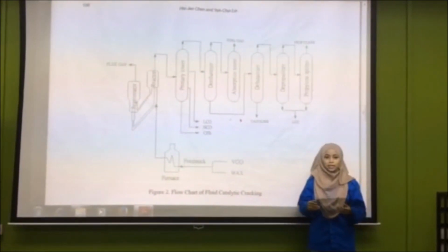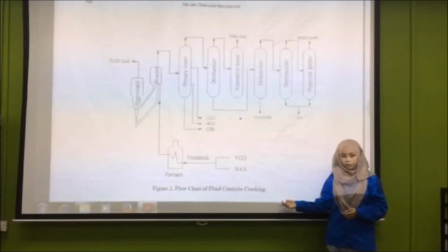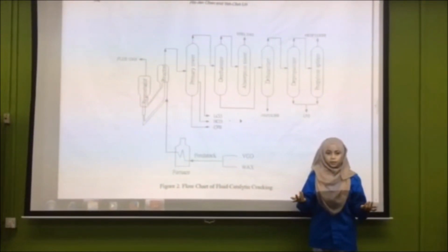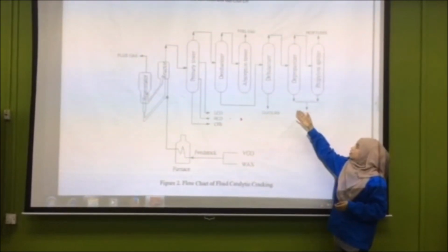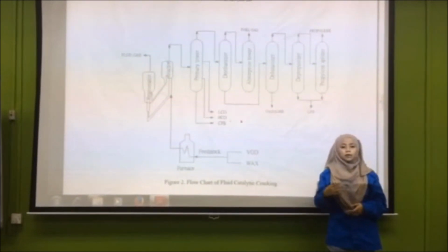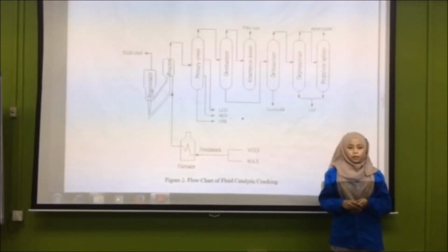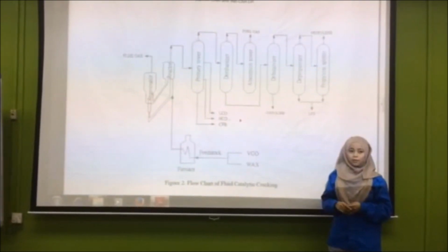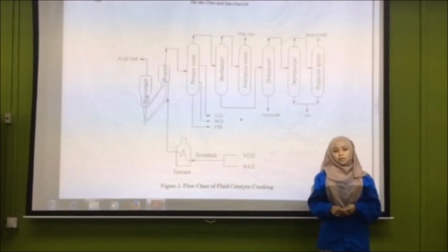The last part is the debutanizer. Figure 2 shows a flowchart of a fluid catalytic cracking process, and the debutanizer is used for separating butanes and lighter from the gasoline product. The feedstock of the debutanizer comes from a butanizer and is 562 barrels per stream day. The debutanizer is to operate at 150 psid. The design specification will require the overhead product to contain 98.5% of the butanes and lighter components with a contamination of 1.5% pentanes and pentenes.